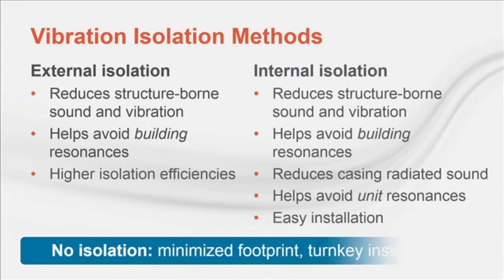Many manufacturers offer direct drive fans with little to no isolation, especially when offered in an array. If the application is right, no isolation is desirable as it results in a minimized footprint and a turnkey solution for the installing contractor. Fan arrays present an additional method. Each fan can be isolated individually or they can be isolated as a group.